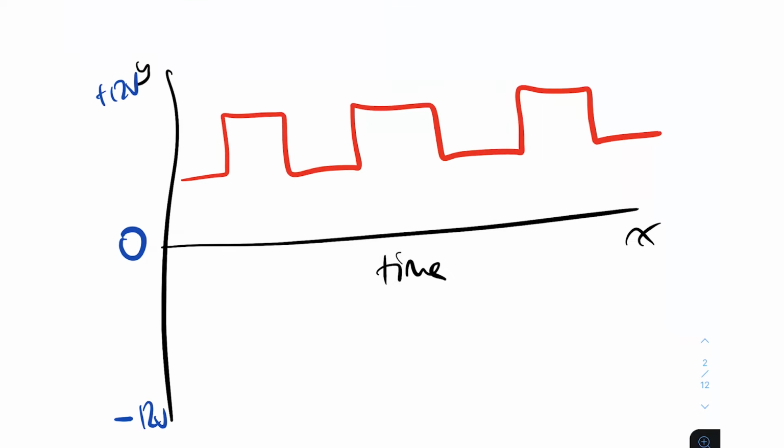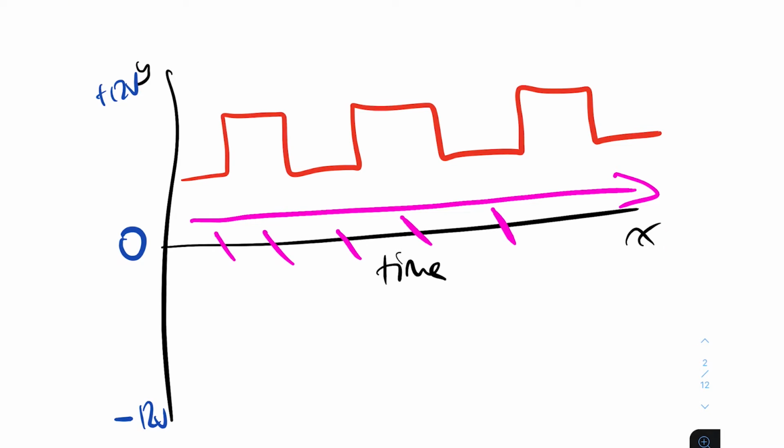All right, so here we've got a waveform. This is called a square waveform. And as you can see, it's going in one direction across with time, but it doesn't cross this zero axis here, right? It stays above. So for example, this is 12 volts, maybe this might be 10 volts, and this could be 5 volts. So you can see it goes from 5 volts here, up to 10 volts, back down to 5 volts, up to 10 volts, back down to 5 volts, right? But it doesn't cross the zero axis, so this is a unidirectional waveform.